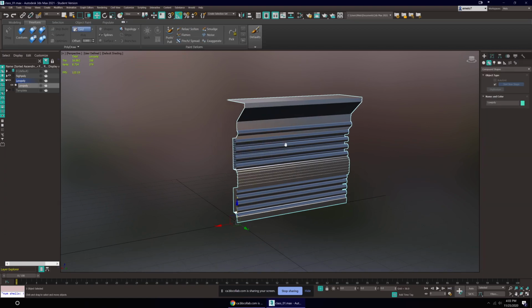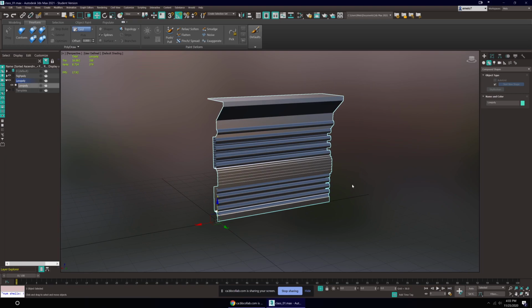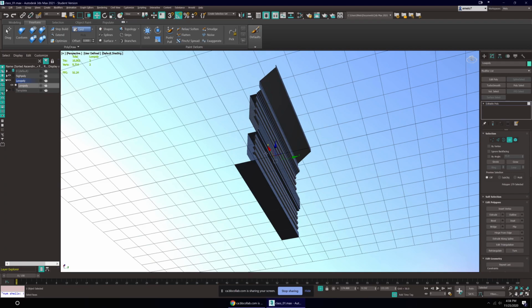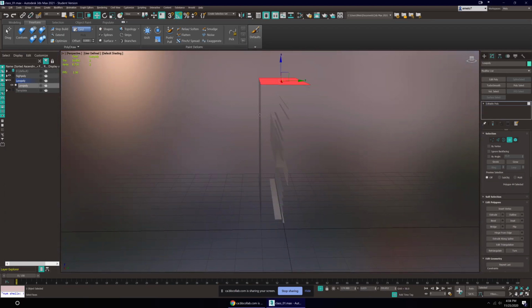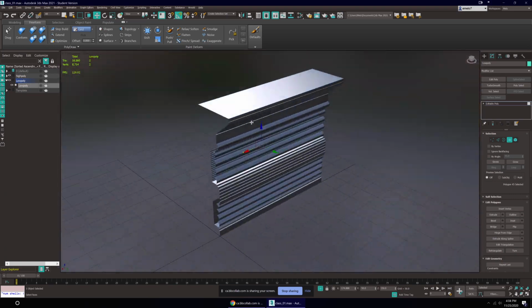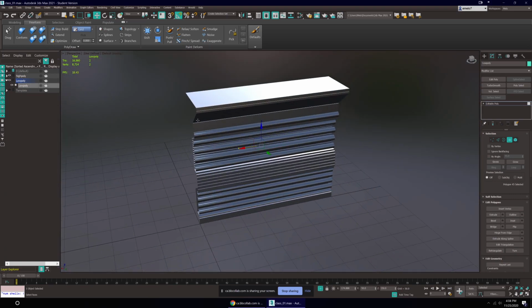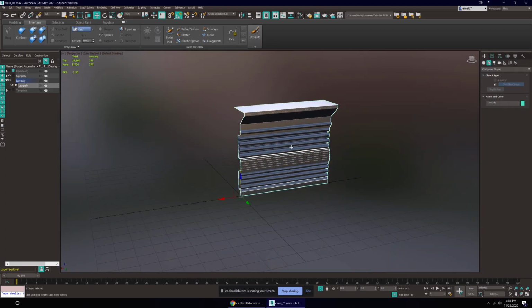I'm going to collapse my whole stack. And we can start exporting this out. Now, before I do that, let me just delete the polygon I don't need. So the bottom one I'll definitely never need. It's only the top you'll need and the back that you'll need. The sides, technically, you'll never need them because you'll have pieces that would block that side from being shown. So now I'll select this, File, Export, Export selected.